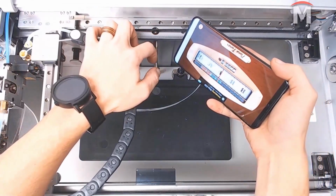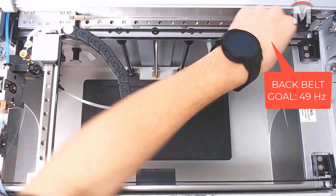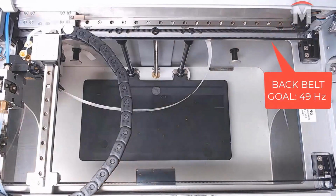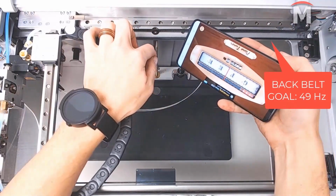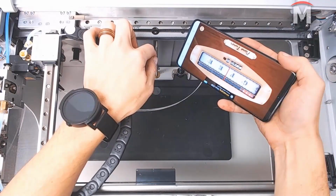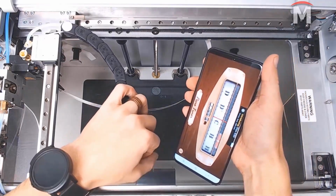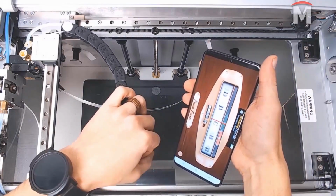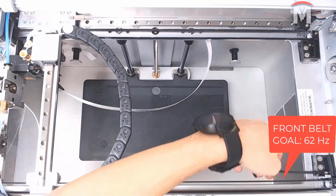Markforged has a really great system for determining the proper belt tension simply using frequencies. So it's a simple tuning app like you use for instruments, especially stringed instruments. There's a tuning app you download. You simply pluck the belt like a guitar string, and it'll register that hertz frequency. And Markforged on their support guide has the proper range that you want to keep these belts in between.